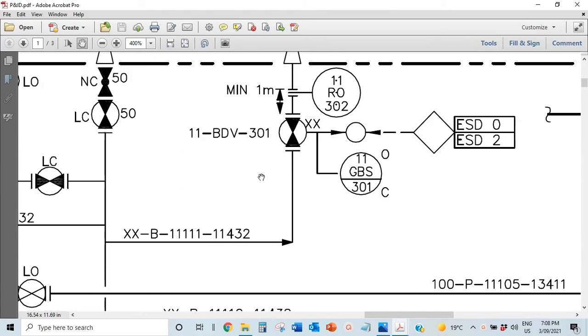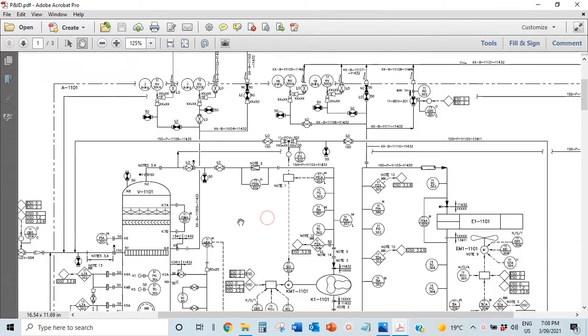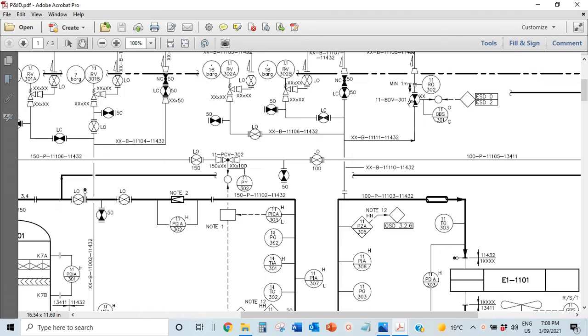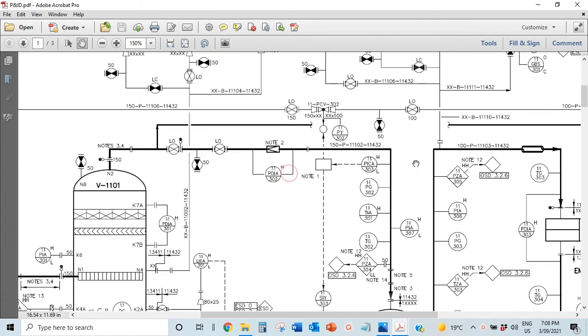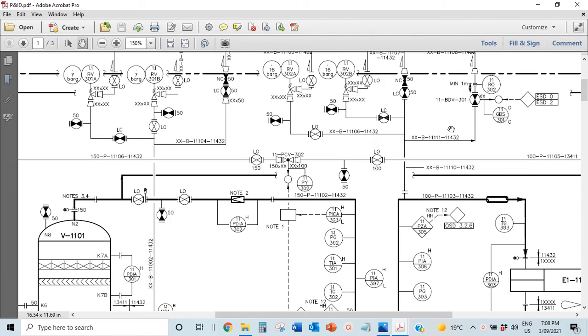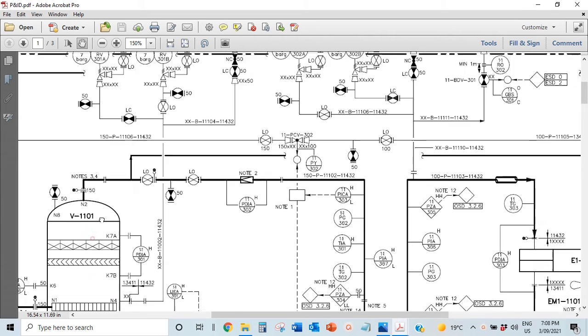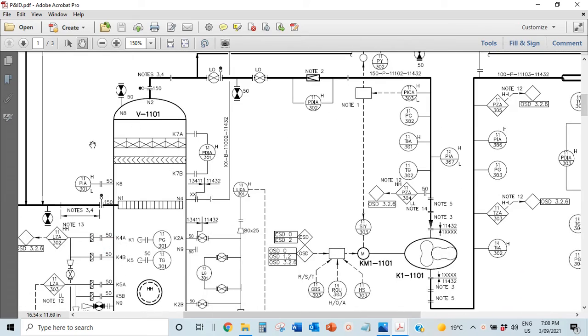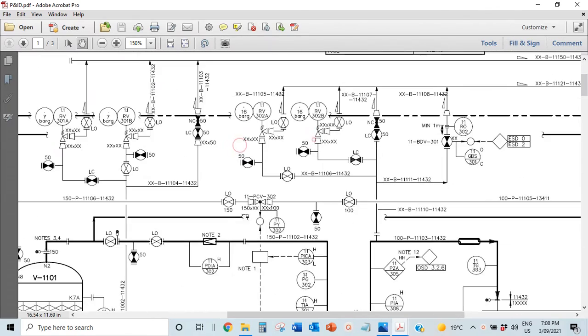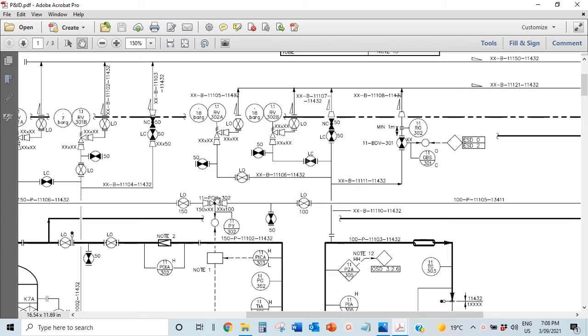This is on the gas line, right? And you don't want your gas line to be pressurized when there's a fire. You don't want gas in here when there's a fire, because you could have it heat up and rupture. So you don't want all that gas trapped in here with the liquid. So the best thing to do is relieve it to the flare.